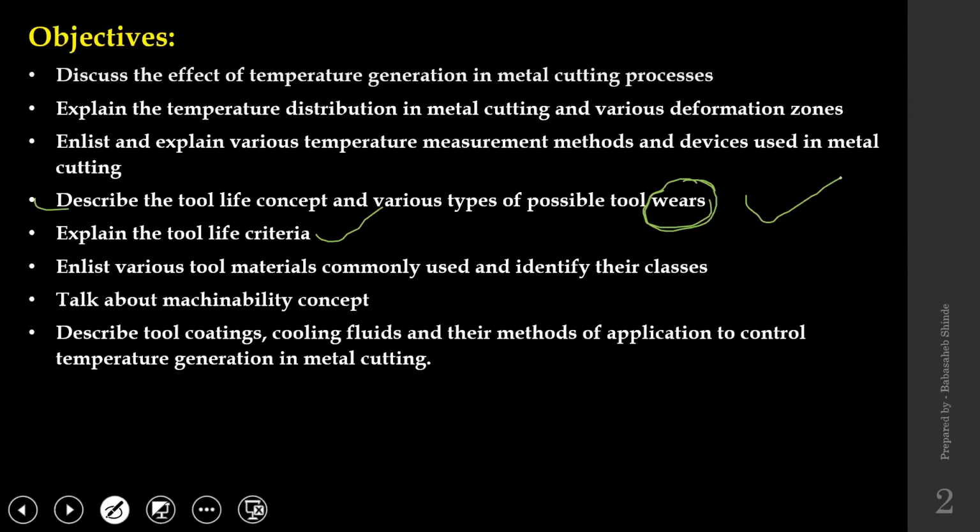Observing that wear on the cutting tool is nothing but the tool life criteria. Once you have got that much amount of wear or that nature of wear on the cutting tool, either go for regrinding of the cutting tool or simply replace the cutting tool.